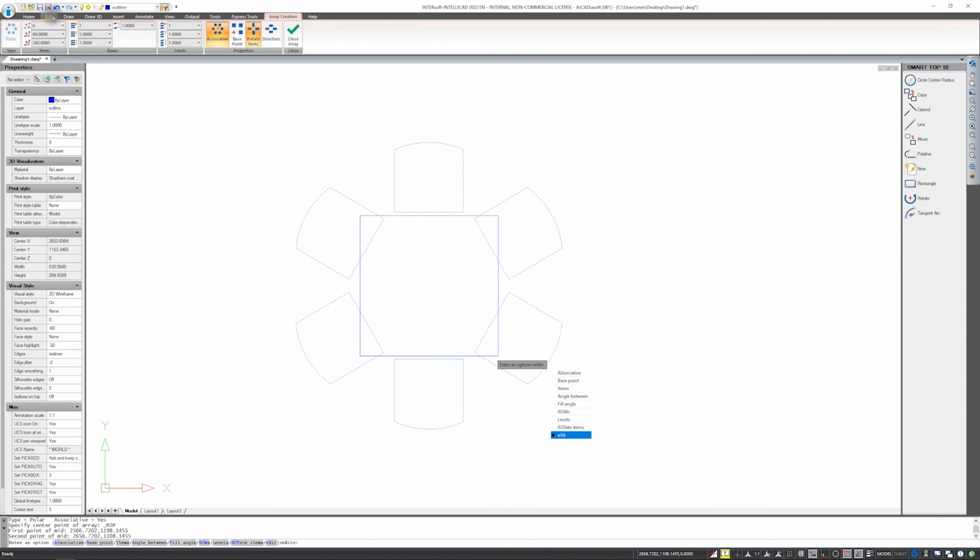And I will only want 4. By default, it goes every 90 degrees. So it is a full circle pattern, so 360 degrees. If after checking these elements, so in this case my chairs here, are to be 1 element, then you choose the array, the associative array. So mark this array. If not, then deselect it.